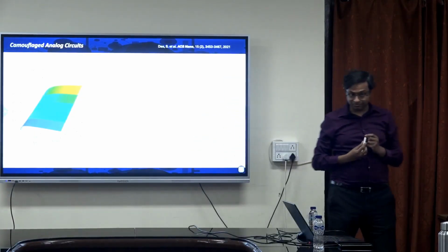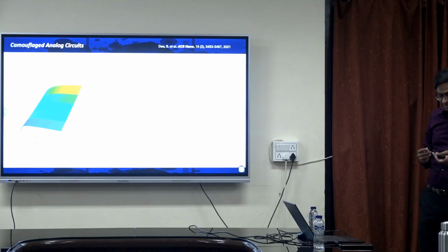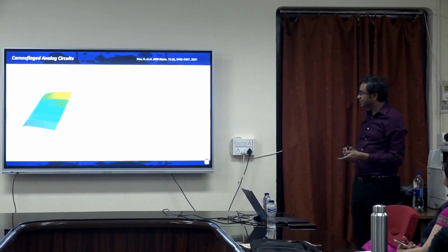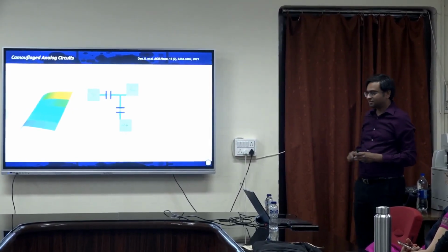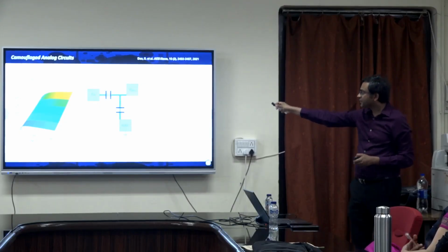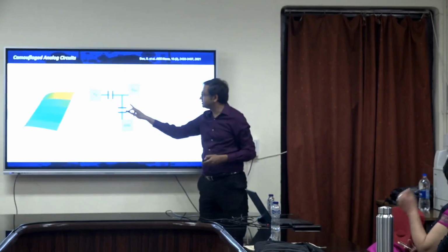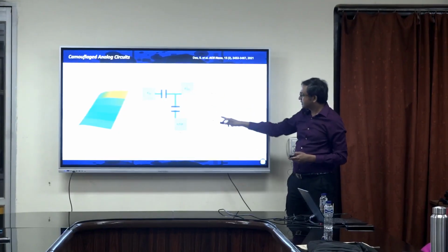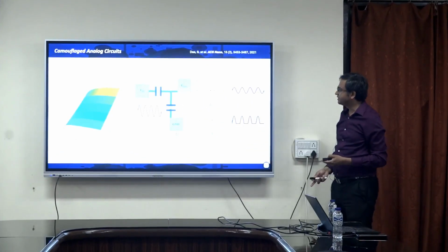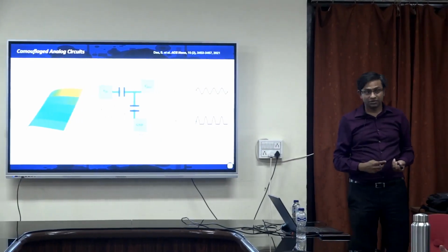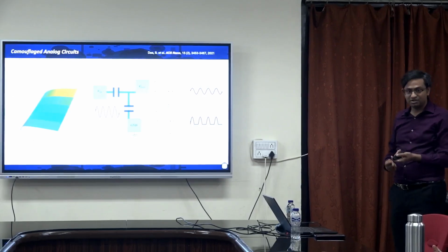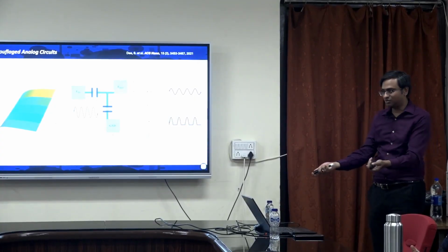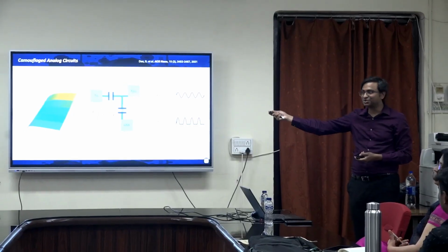So you see the idea of camouflaging, right? If everything looks alike, it becomes exponentially difficult for your adversary to figure out the function. And this is something I have shown you using a simple circuit diagram. Here there are only 2 elements: a resistor and this camouflaged element. If this camouflaged element is a resistor, then it's a voltage divider, and if it's a PN junction diode, then it's a rectifier. The output is very different. So what did I accomplish? I camouflaged my circuit, isn't that true? I don't care about reverse engineering, because you can look at what the design is, but you will have to go through this many trials to tell me what it is actually doing.